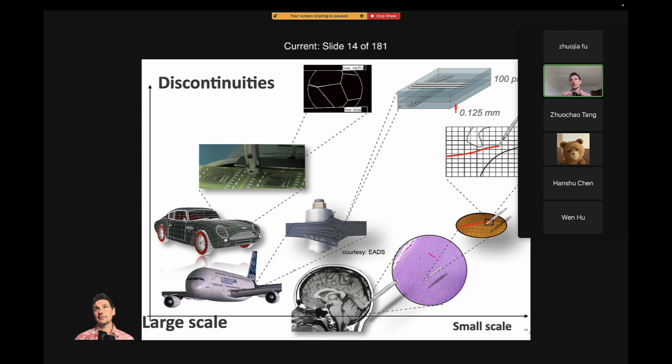So this is what happens at the top here. You have this little solder joint. The solder joint has 1 grain, 2 grains, 3, 4, 5, 6 grains here. It's very coarse solder joints. At the interface, you have a jump in strain. Why? Because you have a different material on the left and on the right. These materials being different, you, of course, have different material properties and therefore a jump in the strain field.